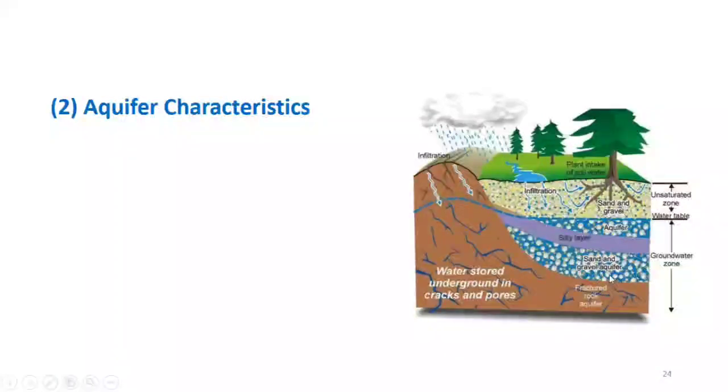Whereas if you look at this sand or gravel layer, it's again an aquifer, but the difference is this is now confined, because you have a silt and you have a kind of rock, a low permeable material at the bottom. So if you have low permeable material on top and low permeable material on bottom, the aquifer will be called a confined aquifer. And in that case, it's quite possible that an artesian condition will exist. When I say artesian, that means if you install a piezometer in this, the level of water may rise above the groundwater table, which is pressurized flow, because it becomes like a pipe flow. Pipe flow is always like a pressurized flow. So you may have a high amount of head in this layer as compared to the unconfined aquifers.